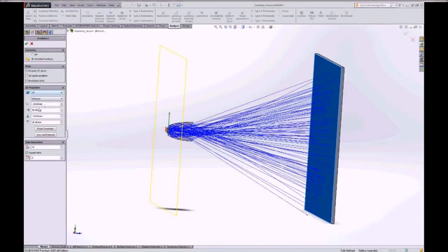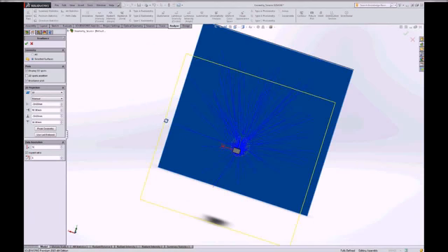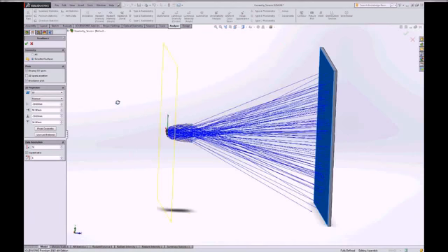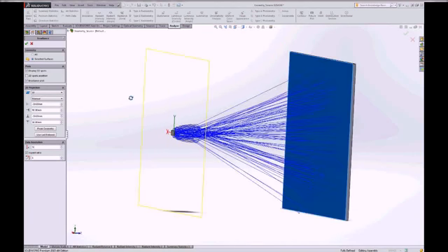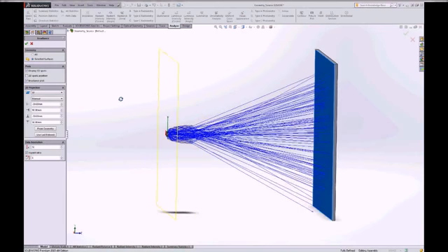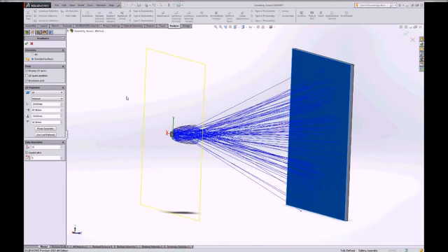But you'll also notice that it sized the analysis region based on the size of the geometry. And it's also made an assumption as to the planar projection of that surface. And in this particular case, that is the correct projection. I have a data resolution, and I'm going to use square pixels. And it remembered that I increased my data resolution slightly to 51 from the default 39.